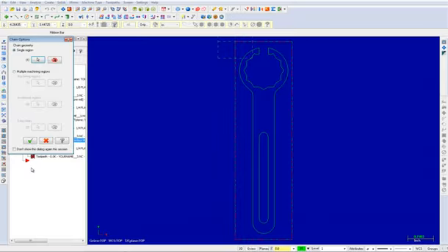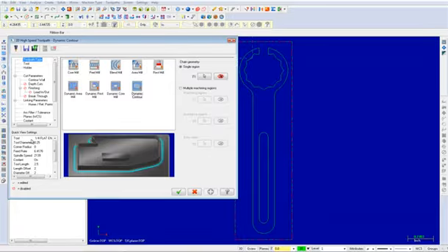When the Chain Options dialog box appears, leave the Single Region option as shown. You can now select the OK button to exit the Chain Options dialog box. From the Toolpath Type page, choose Dynamic Contour and then select Tool from the Tree View list.